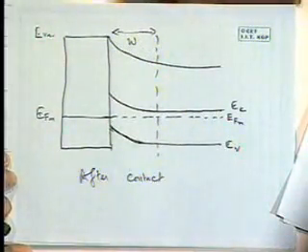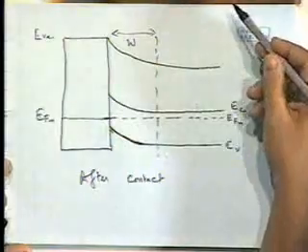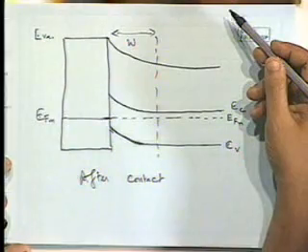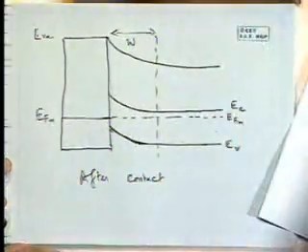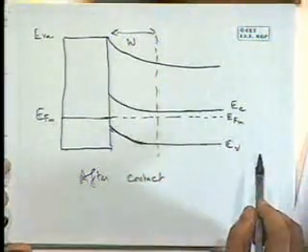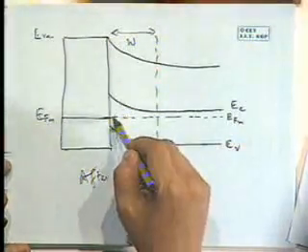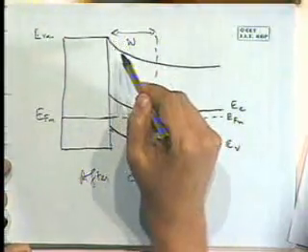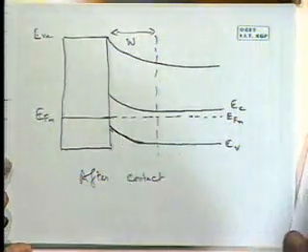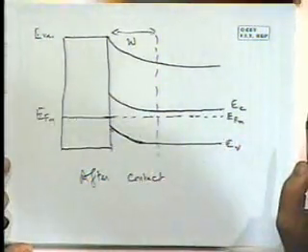Because the amount of energy that it takes to remove there hasn't changed, I'm maintaining continuity. Shouldn't it increase because now the semiconductor has a positive core? No. That is only at this interface. And then you do see that with respect to the Fermi level, it has increased. But in the bulk, nothing has changed. So how much energy it takes to remove an electron from the bulk remains unchanged. And that's why the whole thing is bent.